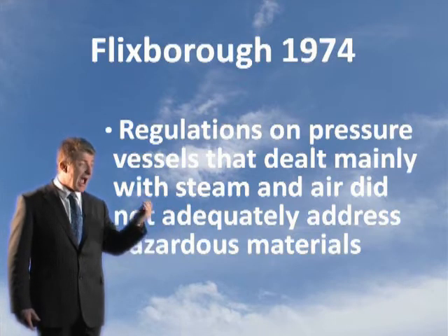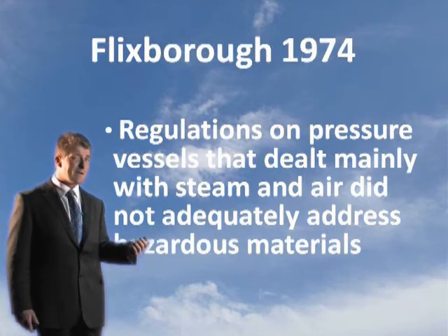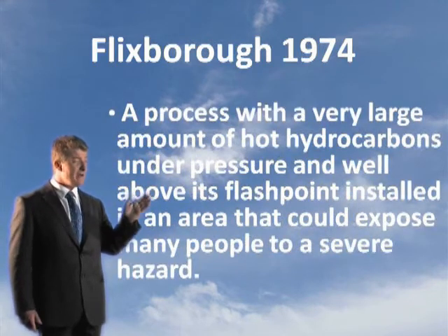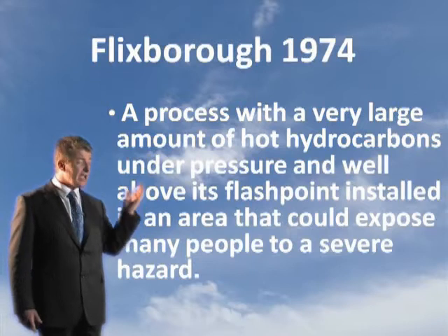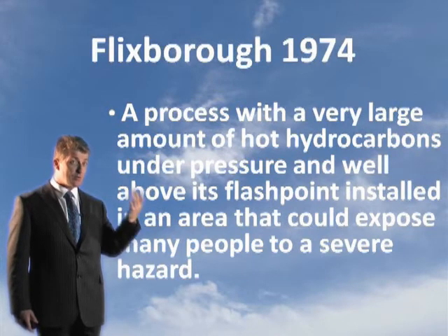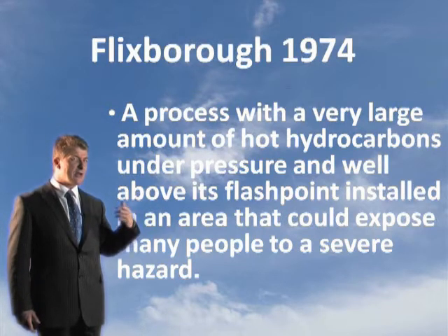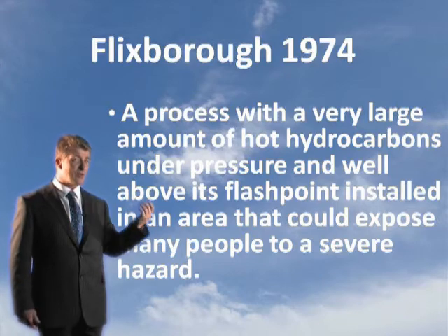I mean, this was highly flammable gases and liquids. A process with a very large amount of hot hydrocarbons under pressure and well above its flash point, installed in an area that could expose many people to severe accident, was not addressed. So, that was Flixborough, an unconfined vapour cloud explosion.